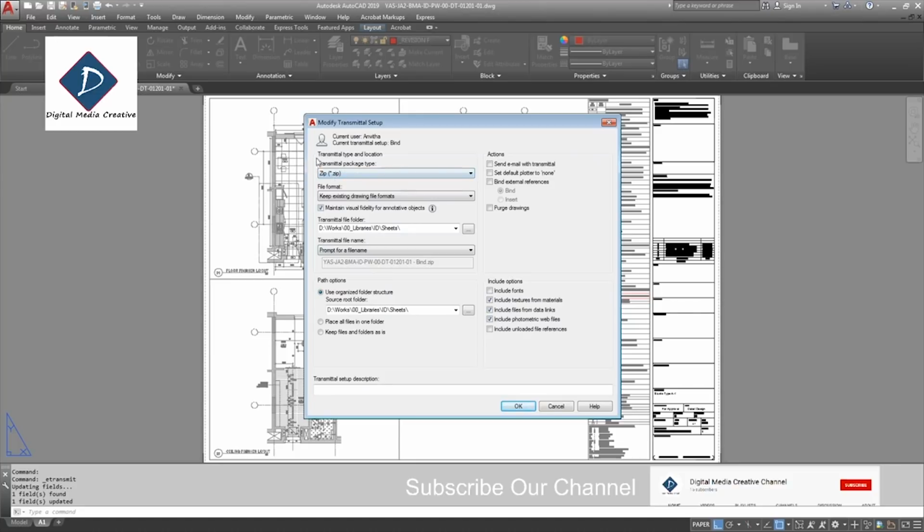For the transmittal package type, I'm always choosing folder set of files, and for the file format you can keep it as it is for the existing drawing file format, or if you want a lower version, you can easily click here. Then whenever it binds, it automatically goes to the lower version. For now I'm just keeping the same as it is.